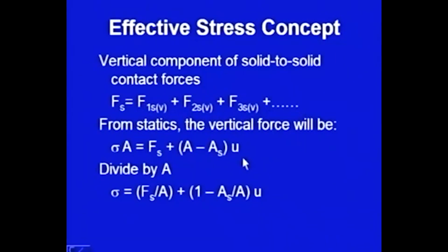Now, from statics, you know that the total vertical force, that is the total stress into area, will be equal to the force borne by solids plus the force borne by the pore water. So, sigma into A, where sigma is the total stress which I calculated earlier and A is the total cross sectional area. From statics, this equation should be satisfied.